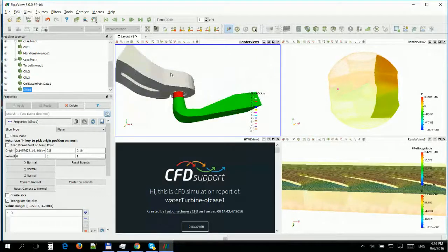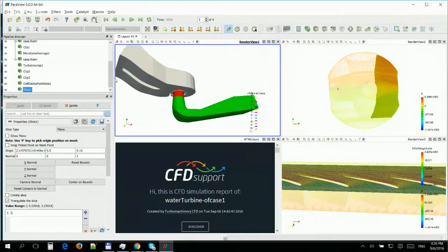Currently, in this version, from the autumn of 2016, there will be a new version of Turbomachinery CFD, and it will be fully, absolutely 100% possible to run periodic segments. So yes, from late 2016. But with the current version, which is 16.06, the version from June 2016, you should do one step manually.